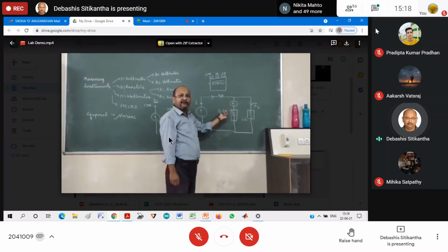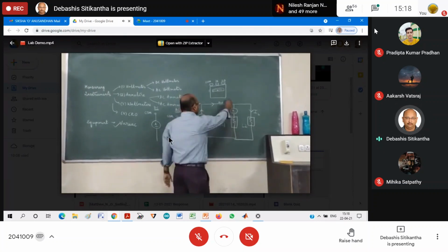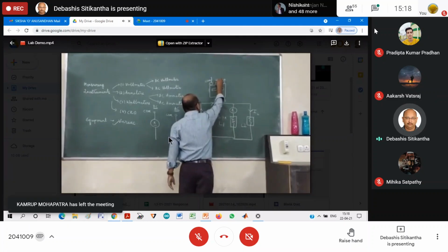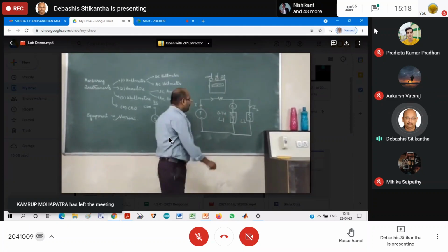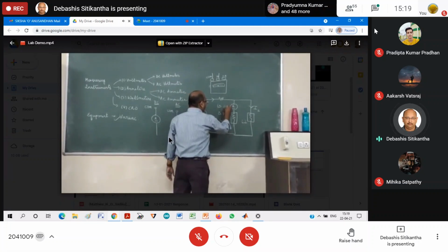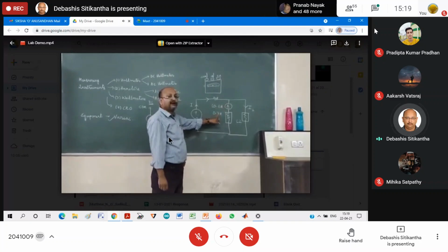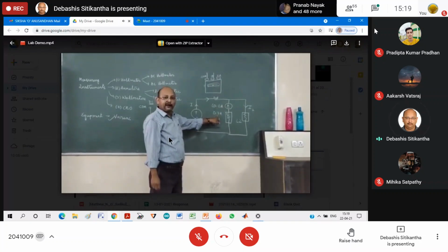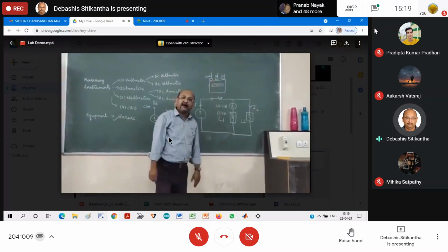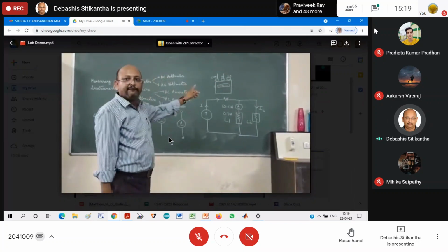In the next step, we will disconnect the supply and connect it between 0 and the 1 ampere terminal. We get the reading between 0 to 1 ampere only after making sure that the current is 0.7 ampere. If it is unknown, always connect it to the highest setting or the highest rating of the knob available.